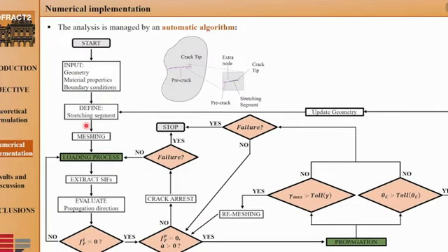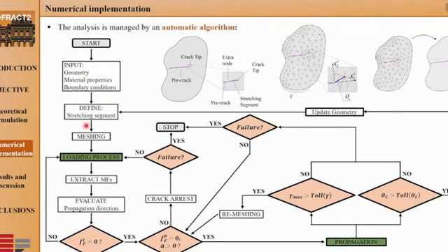During the propagation, the elements around the crack tip distort because of the motion of the mesh nodes, and the remeshing process is required exclusively when mesh regularity is compromised. In addition, a tolerance to the angle variation of the stretchy segment with respect to the local crack system is imposed, and when this tolerance is fulfilled, the computational domain is updated. So the analysis continues until either crack arrest condition or the collapse events occur.